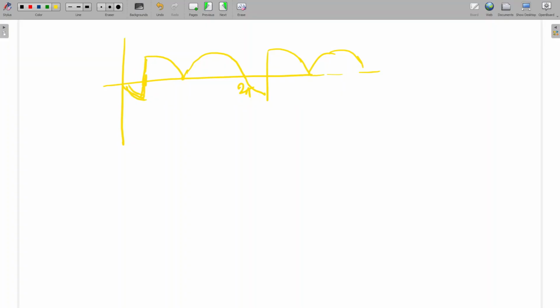I see a question like this can be framed. They can ask T1 T2 at alpha, and this sequence will be repeated. In the next cycle they are firing T3 T4 at pi. We can say this is pi, this is 2 pi, 3 pi, and this is T1, T2 at alpha.